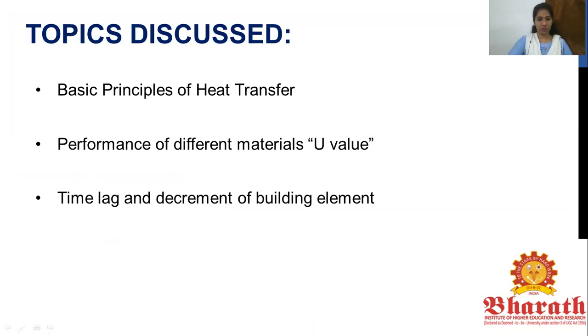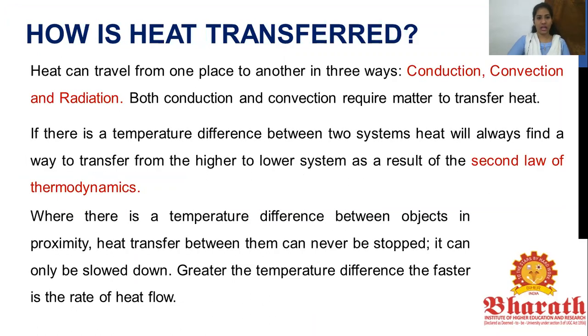Okay. The topics that will be discussed are the basic principles of heat transfer, and the performance of different materials considering the U-value, the time lapse, and the decrement of the building element. Looking at the basic principles of heat transfer, we'll be looking at how exactly heat is transferred. Heat can travel from one place to another in three ways: conduction, convection, and radiation.